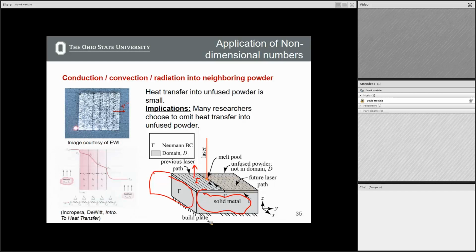Sorry? So, the example you just gave, it should be perfectly flat, right? Okay. So we're just assuming that the powder is smooth enough that there's not enough flow. That would be an assumption. If the Biot number is getting a little bit closer to 0.1, then maybe we would have to be a little more careful with that, but we were pretty far away. Well, in fact, we're 4 away from that.